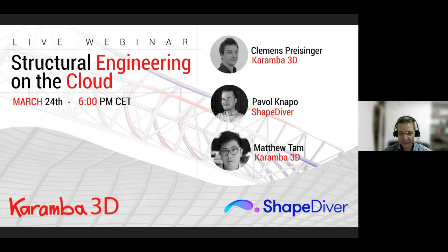Maybe we keep a bit more to the Karamba questions at the moment. Someone asked, does Karamba take account of stability and buckling effects in the cross-section optimization component? Yes, it does. It does so according to Eurocode 3. So you have to define a buckling length, and it also includes lateral torsional buckling, where you also have to set the corresponding buckling length. So it does take account of stability in this specific way.